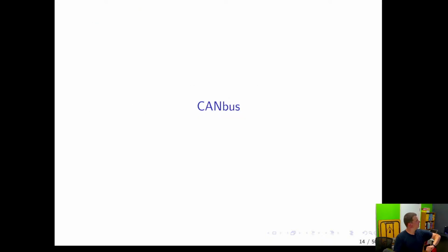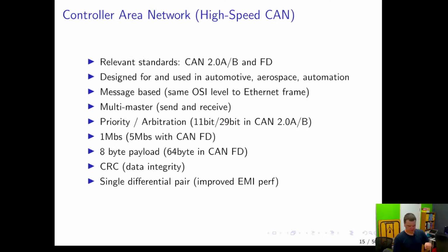Cool. So, quick background. Now we are talking about the CAN bus electrical interface itself. This is basically a messaging standard designed for automotive, mostly automotive and automation. There's a handful of standards and a bunch of historical nodes that don't really matter. It's interesting, but not relevant. So we're only going to talk about CAN 2.0 A and B, which are called standard and extended, and FD-CAN.